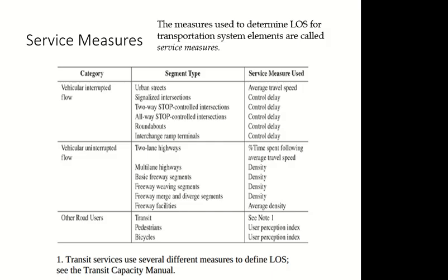Okay, and then there are facilities which are for other road users such as pedestrians, bus passengers, and so on. So they have their own method. Okay, so the method is different. The method is shown with all the calculation examples in the Highway Capacity Manual, but it is not part of this course. So you can see here mainly for interrupted it is delay, for uninterrupted it is density, and then we have exceptions where you need average speed and percent time spent following for the highway facilities.